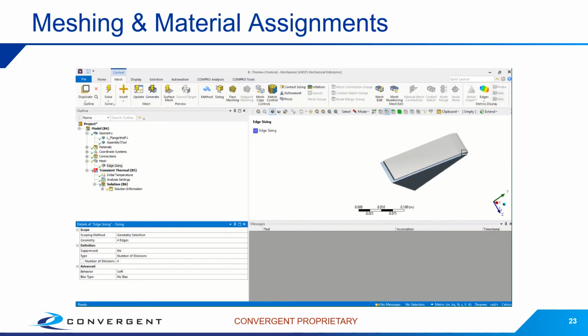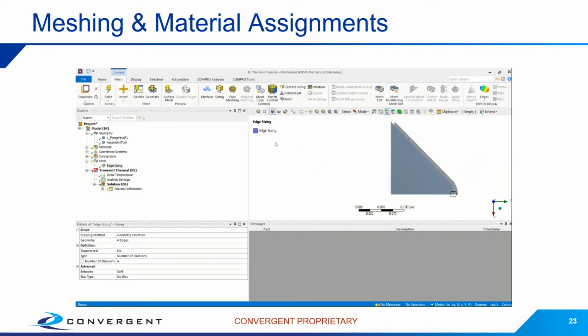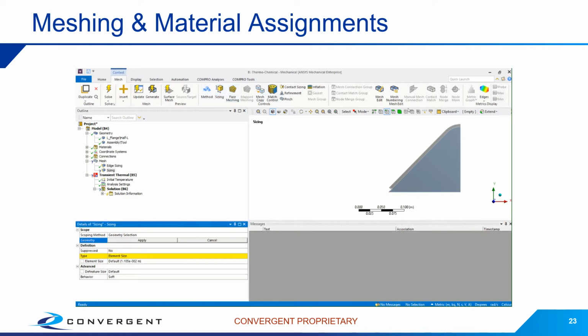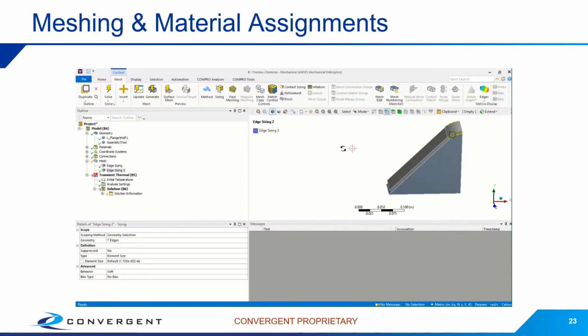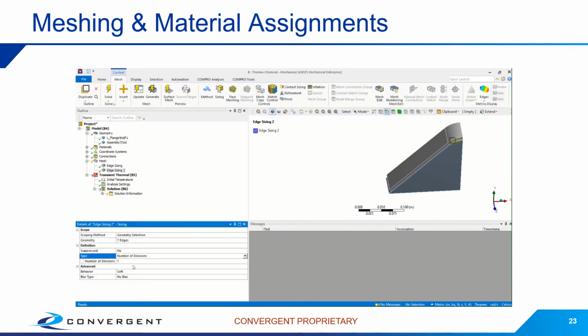I'd like to refine my corner. So change that view a little bit. Apply another sizing condition. Change this to box select and drag from right to left to select all of my corner edges on the part and the tool. Change this to 12, nice and refined in there. And I'm going to change the sizing as well. So the sizing I'll apply to the body.